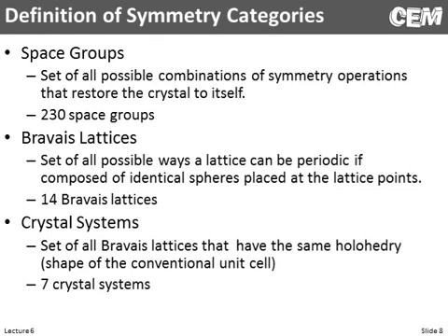And if it's not, a lot of times the analogy still holds. Instead of an arrangement of triangles, we'll say it's an arrangement of spheres. But anyway, if we can just say we have an arrangement of spheres, all of these 230 space groups reduce down to the 14 Bravais lattices. And we can also then divide it also into 7 crystal systems, as you'll see. That's the next slide.